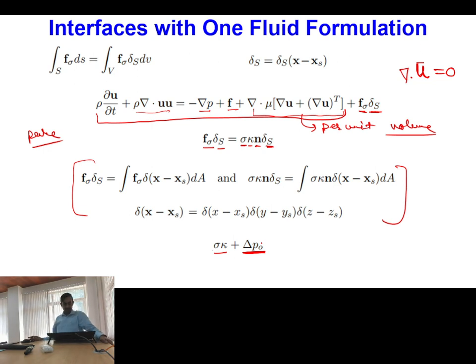Okay, so this is how some of the people in the past have compared the bubble dynamics of contaminated or non-contaminated bubbles. So for a pure system they have used the actual sigma k, and for a contaminated system they tried different values of this additional pressure drop, and then they tried to see for what value their system is actually behaving exactly like the experimental system. And this is how some ad hoc arrangement can be done to simulate the contaminated system.